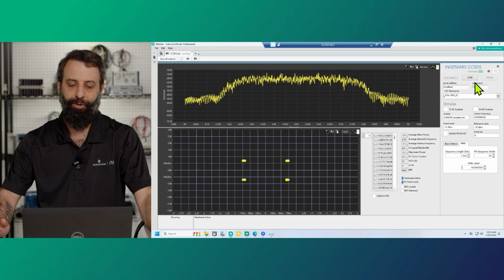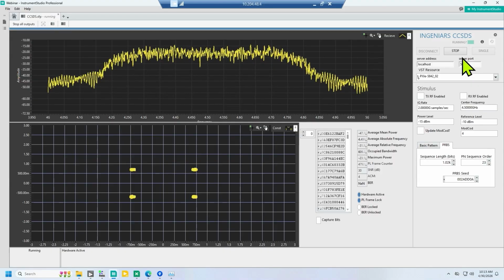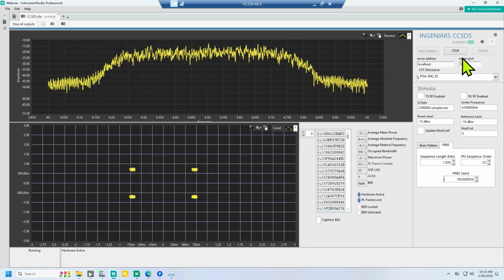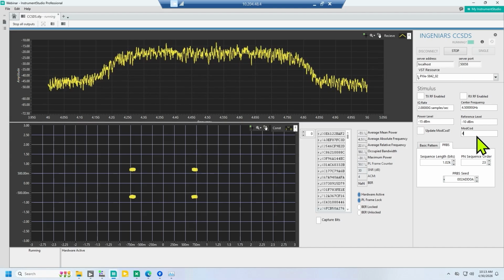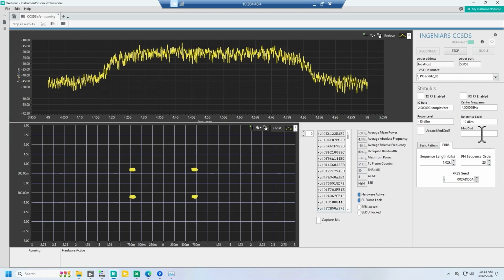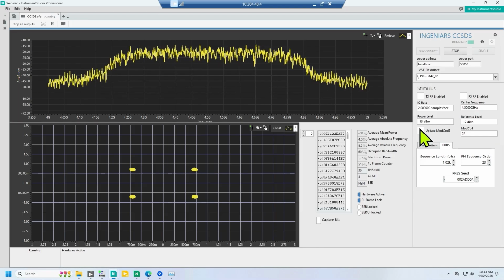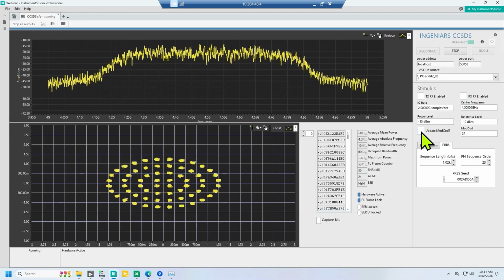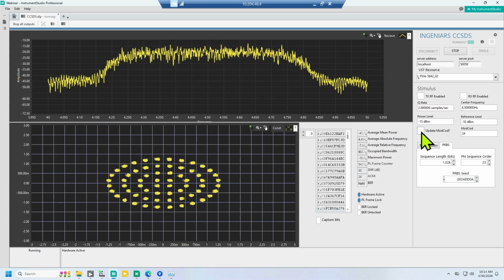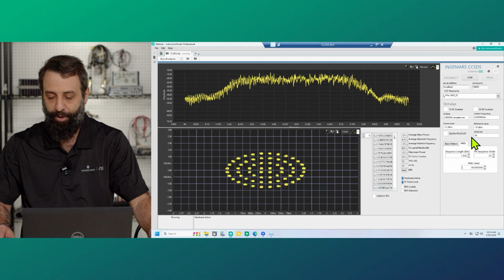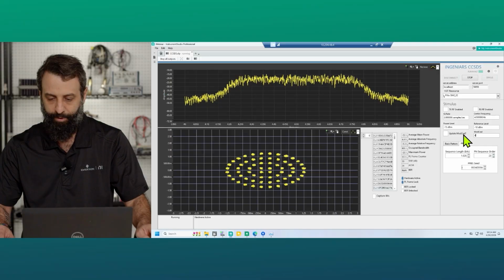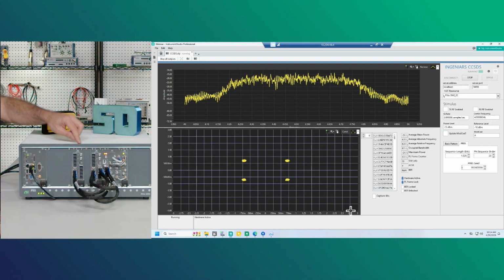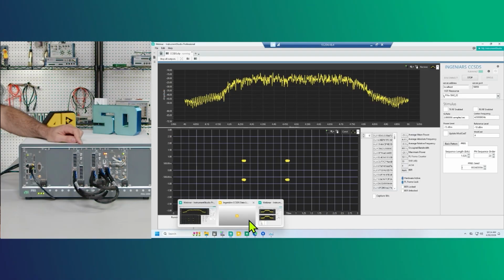On my screen, I'm showing you a basic QPSK signal being modulated, sent and received. I can easily change that to other modulation schemes, something like a complex 64 APSK, and we can see that constellation update. But I'm not just sending it back and forth through the VST. I'm also sending it through a second coprocessor and doing what we call channel emulation.